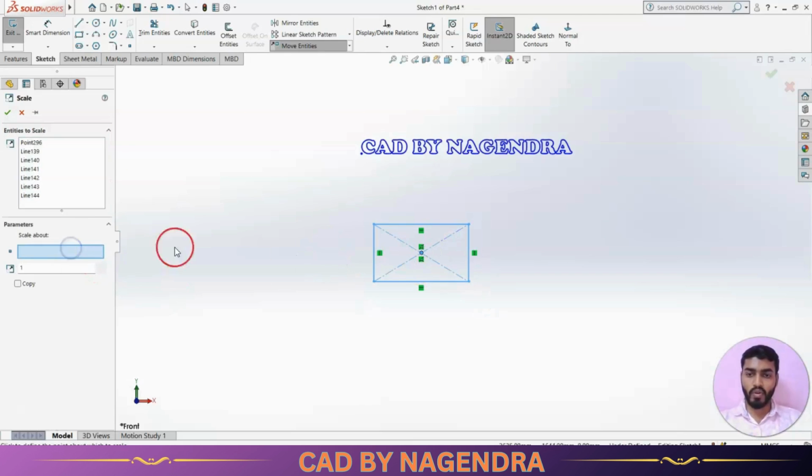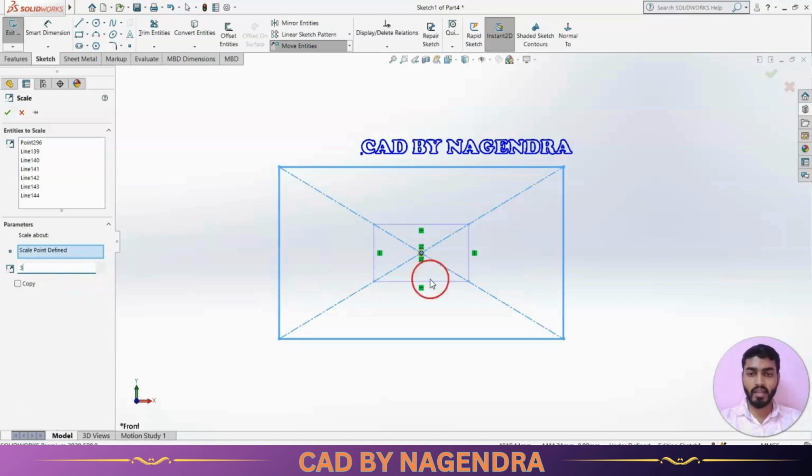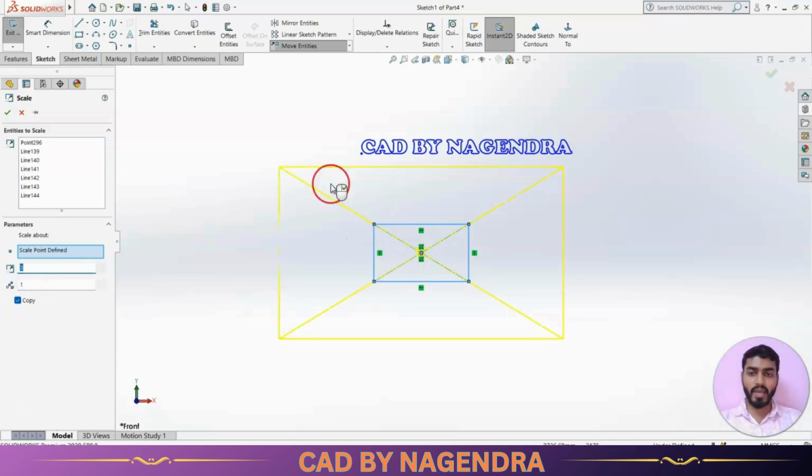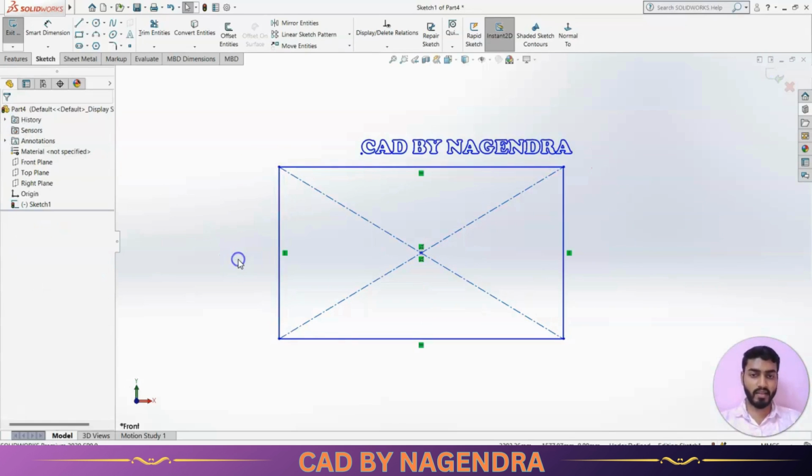Then scale about with reference to any center point. If I give here 2, this entire shape will get doubled. Now if I give here 3, it will get tripled. Like that, we are able to increase or decrease the size of the original one by using this scale ratio. If you are using the copy option, the original also will be there. Extra duplicate feature will be created with the given scaling. If you turn this off, only the original will be changed in dimension with parameters like this. That is the use of scale.